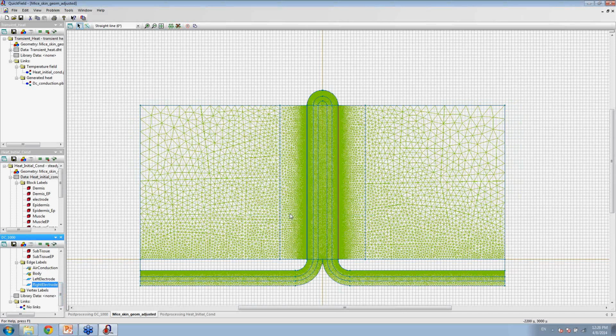Then we need to give the properties of the material, the electrical conductivity in this case. Next, we need to give the boundary conditions. So in this case, again, it's how much voltage we apply for each electrode. Then we need to mesh. In this case, we already meshed it, but in order to mesh, we just push this button. It's called build mesh, then we get mesh everywhere. And finally, we just push the solve button, which is here.